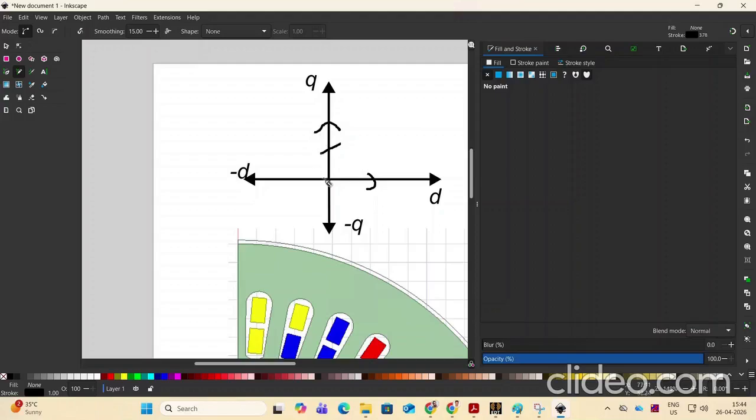So at what internal power factor angle will the torque be maximum? We have to determine that. Suppose this is the current vector, and this is the angle, that is gamma, the internal power factor angle. So where would the torque be maximum?